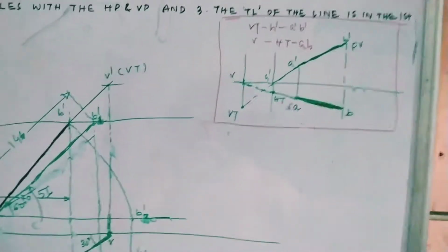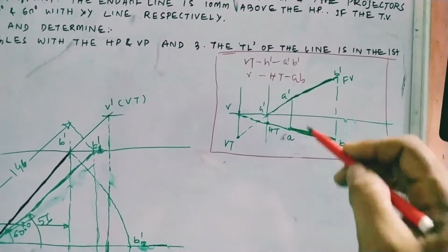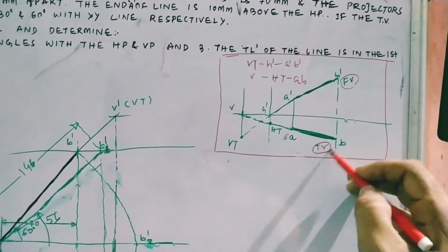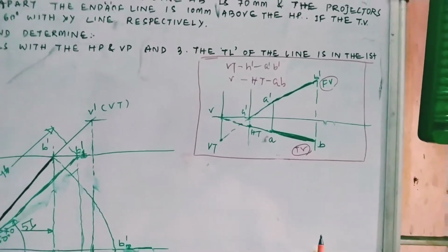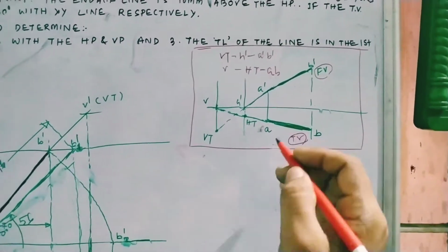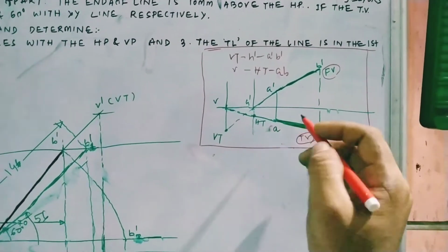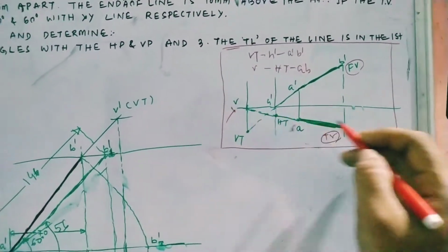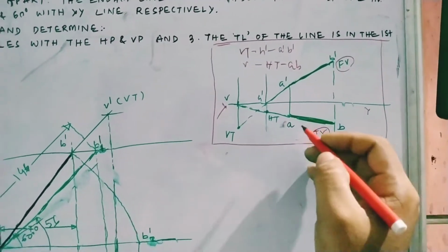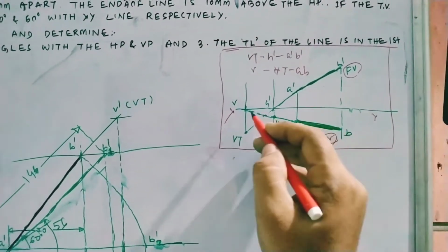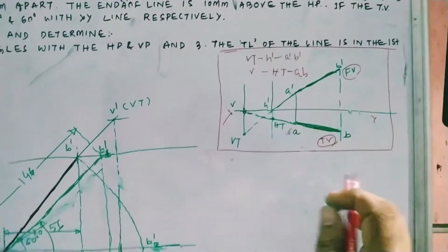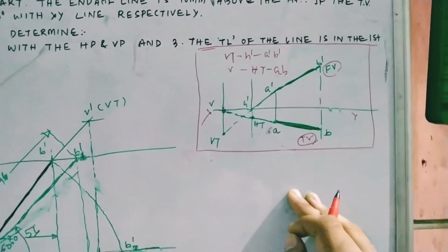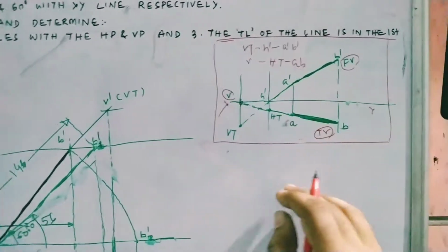Okay. So normally for drawing any top view and front view, I can get this will be my front view and this is the top view. For finding the traces, what we need to do? We need to extend our top view and the front view towards the reference line. So this is the reference line XY, and I'll extend this top view towards it. So I'll find a point where it will intersect with the horizontal line. You can mark that intersecting point like as V.